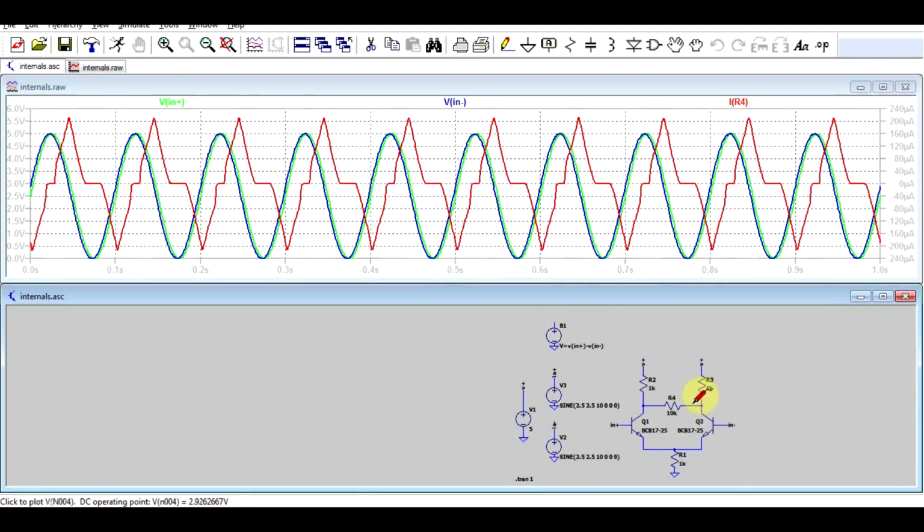through the resistor. Now the first thing you may notice is that if you actually compare the two input voltages, always one of the voltages is higher than the other, except for very small amounts of time when the two voltages overlap. But in practice, the output of the OpAmp has these flat areas, which are quite wide. So for a certain amount of time, when both voltages are approaching the 5V supply limit of the circuit, the comparator output flattens out, and the same thing is happening when the two voltages approach the negative supply line, so at 0V. Again, the output of the comparator is flattening out.